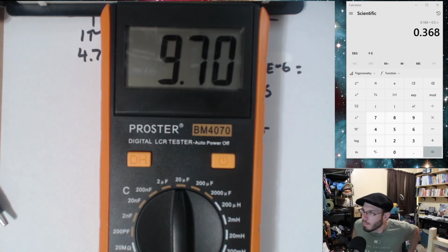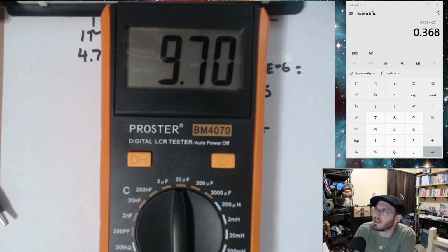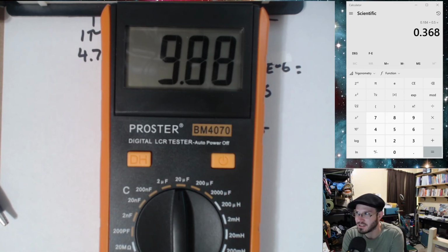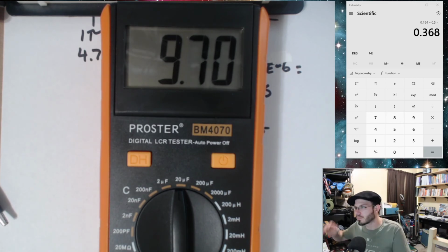Keep in mind, if you're expecting a 100 microfarad cap to be exactly 100 microfarads, for an electrolytic cap, plus or minus 20% is quite a big difference, and that is still considered acceptable margins. So you don't expect accuracy where you aren't going to get accuracy, and that's one of those things you'll learn a bit by experience.